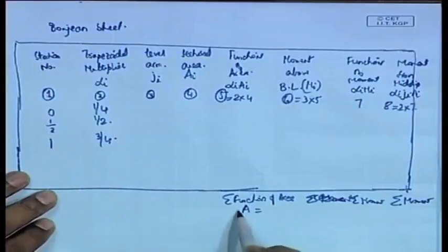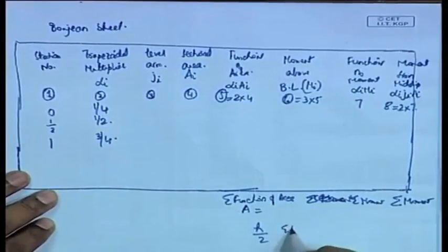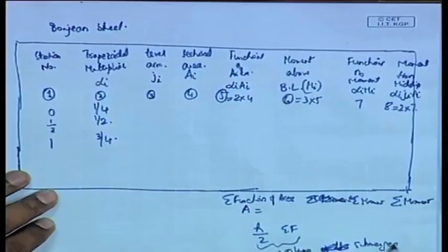So, using this sheet, this is known as a Buoyancy sheet, and using such sheets you can always calculate the total volume under the water from this by multiplying it by h by 2 into sigma function of area. You will get the total volume of the underwater portion, or volume submerged. You will get the volume submerged.